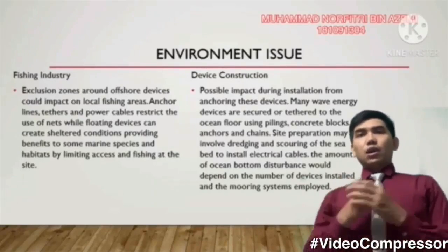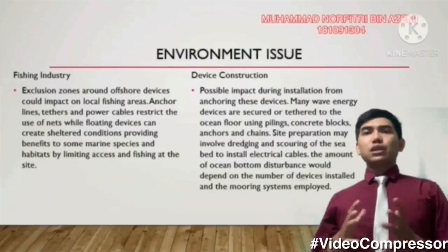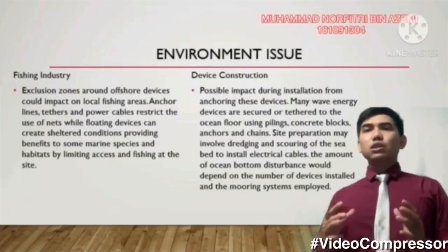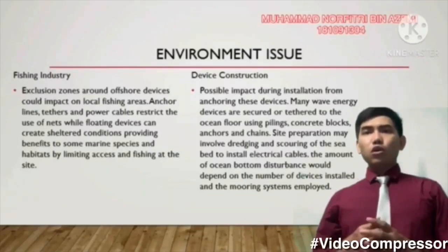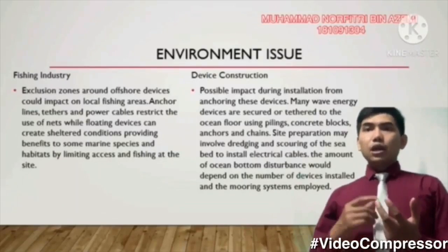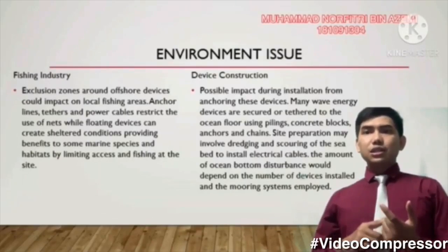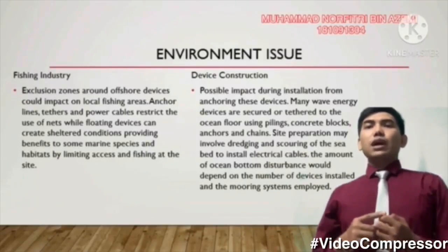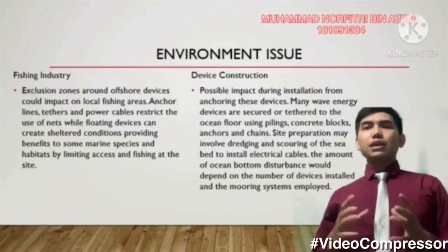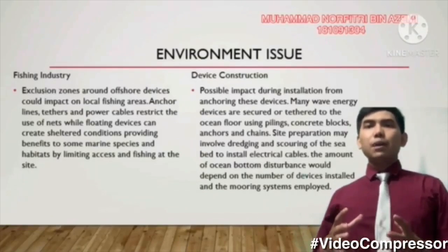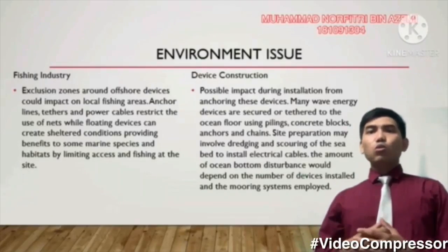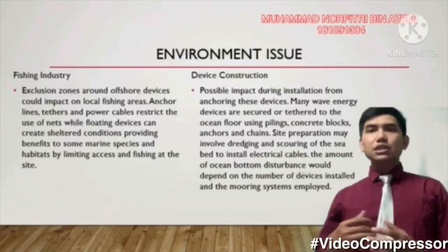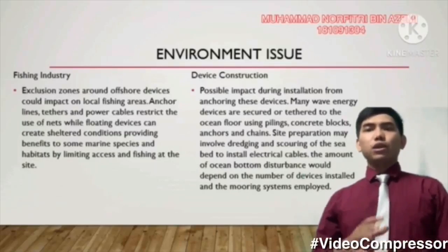Second environmental issue is device construction. Possible impact during installation of the offshore device. Many wave energy devices are secured to the ocean floor using piles, concrete blocks, and chains. Site preparation may involve dragging and scouring of the seabed to install electrical cable. The amount of ocean bottom disturbed will depend on the number of devices installed and the mooring system employed.